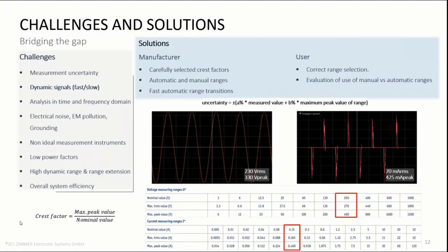For example, let's imagine a current which can go as high as 10 amps under heavy but only occasional load of the DUT, but the steady state current is 2 amps. Using the range of 10 amps to measure this will save us from range transitions, but will force the measurement of 2 amps to happen at a higher range with an unnecessarily high uncertainty due to that range component.